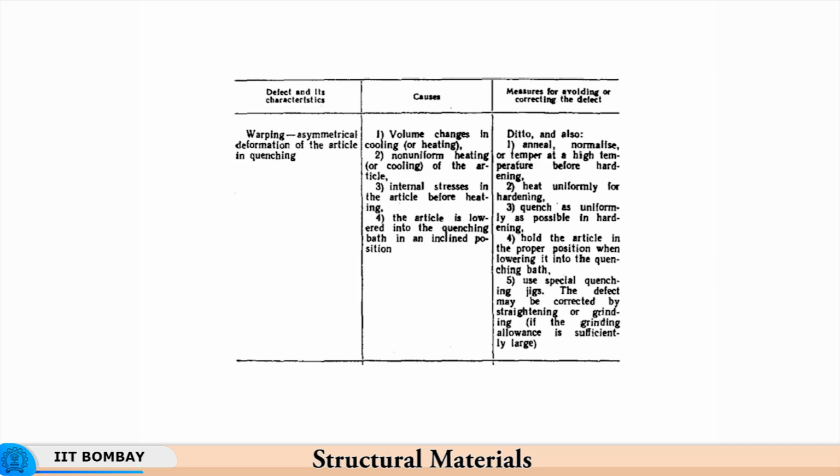So, basically the design of the heat treatment should be such that the jigs restrict the extent of warpage. They may not be able to restrict it completely, some warpage might have to be allowed, otherwise if the jigs are too firm, they might result in cracking.